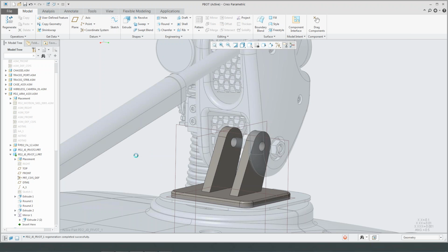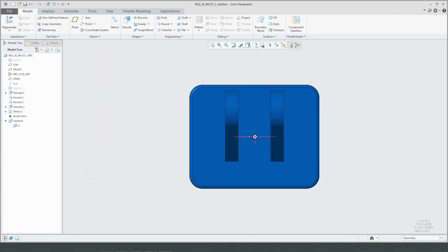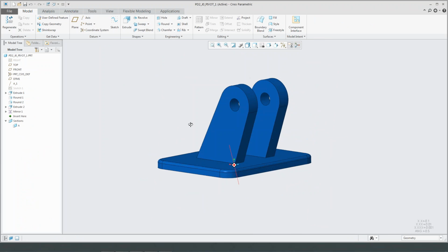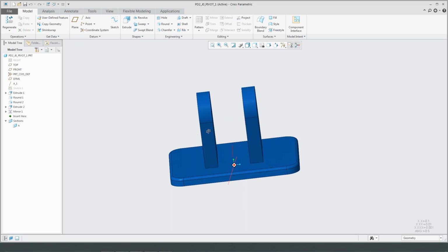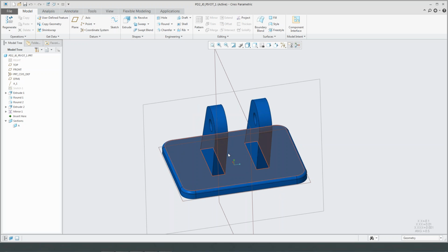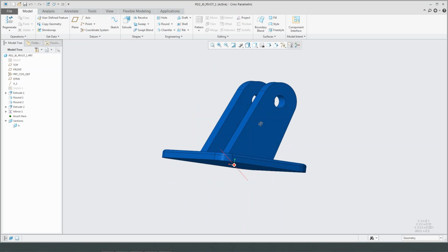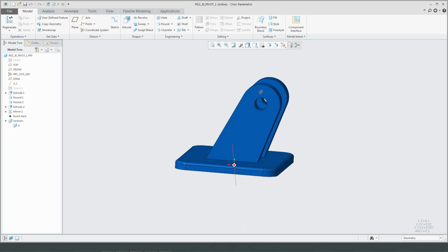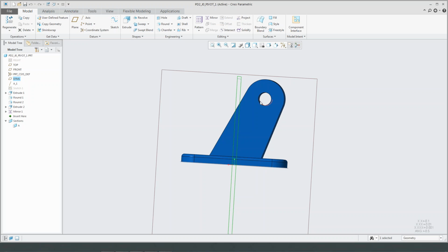Now, let me also open up this component to showcase some more tools that we added in here. So if we wanted to, say, take this base plate and build upon it, maybe we want to give it some more strength in the center here. So maybe we want to create another extrusion between these two boss cutouts here. If we look at this datum plane though, it's not really centered because these are slanted. So I would probably want to create my extrusion off of something more centered.